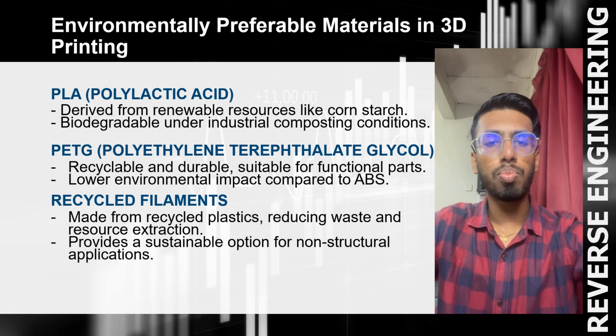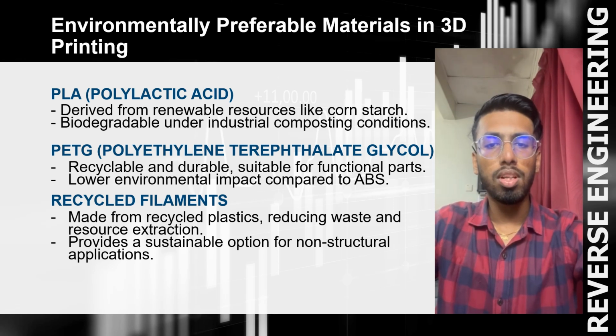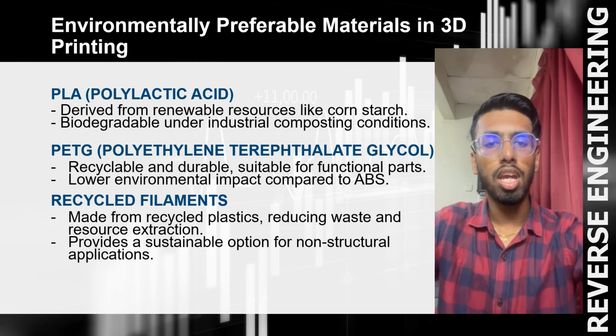PETG stands for polyethylene terephthalate glycol, which is recyclable and durable. PETG is a thermoplastic that combines the durability and strength of ABS with the ease of printing associated with PLA. It is recyclable, making it a more environmentally friendly choice compared to non-recyclable materials. PETG can be reprocessed and reused, which reduces waste and aligns well with circular economy principles in the door latch project.